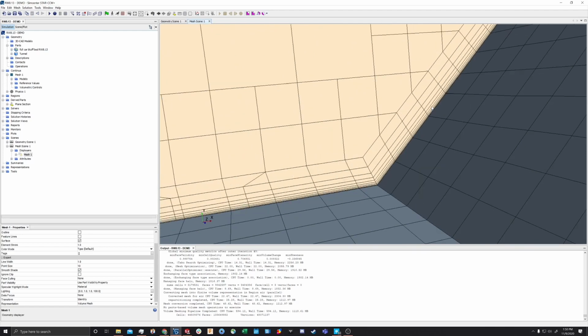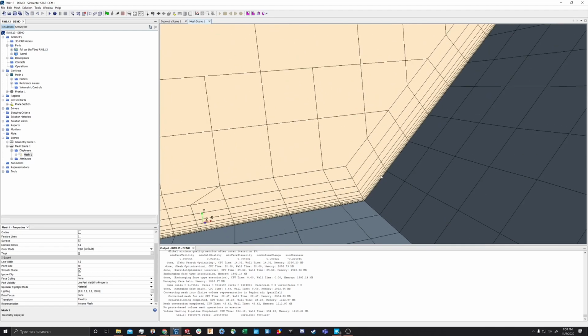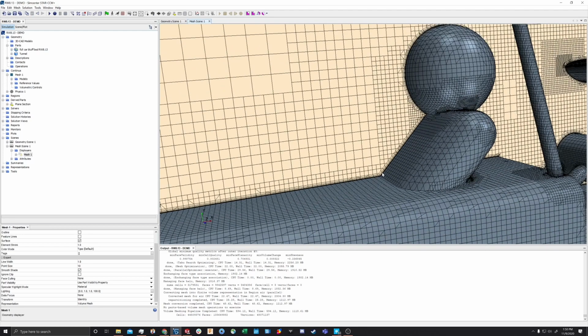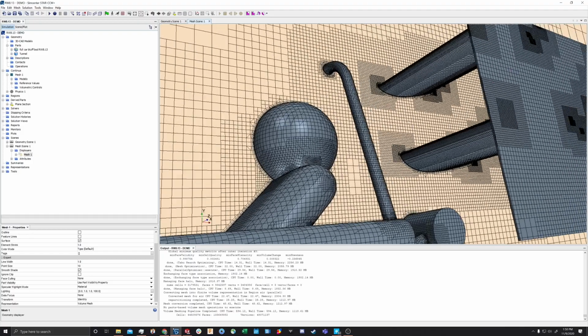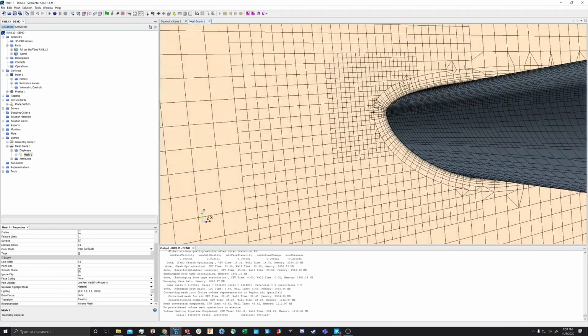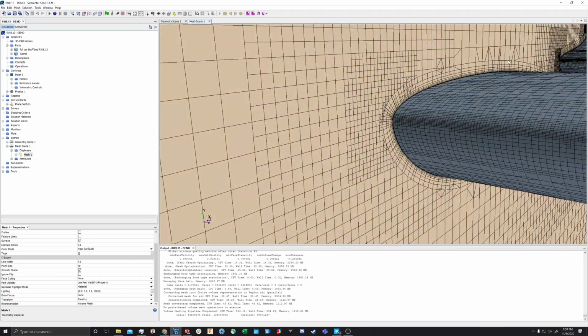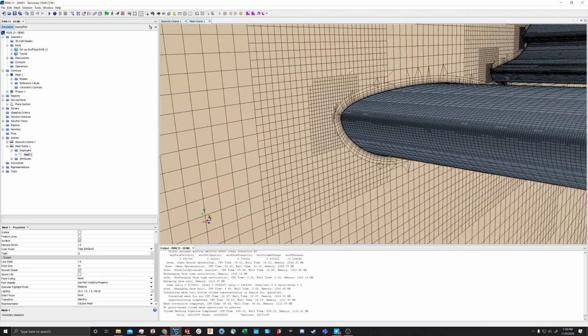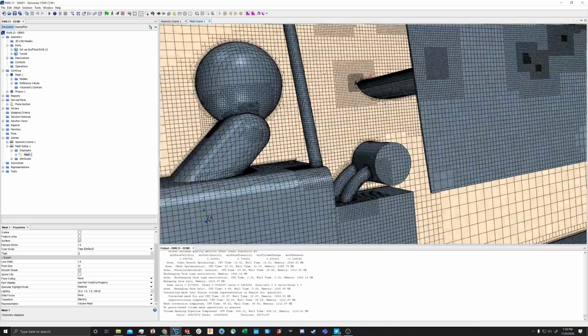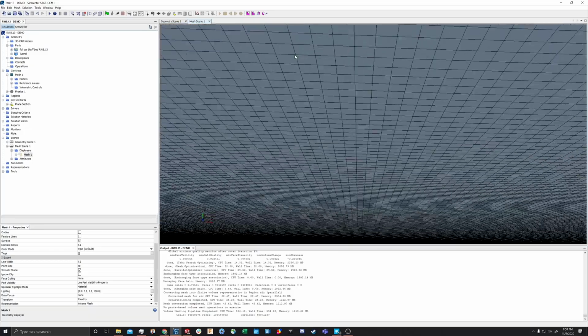You've got these little rectangles that get really fine as you get closer to the surface, so you get a really nice boundary layer flow there. And you can see that here. It's most important on the airfoils. Make sure you've got nice, good sized prism layers there, and then you can also see the size.